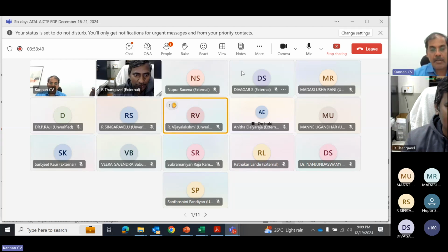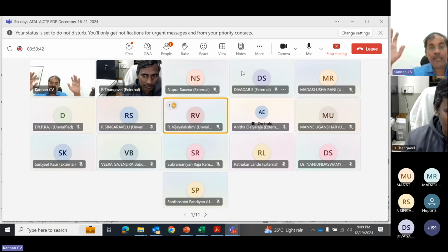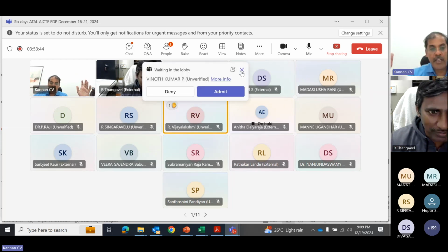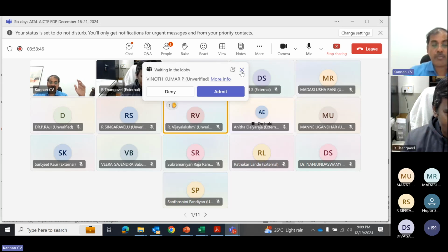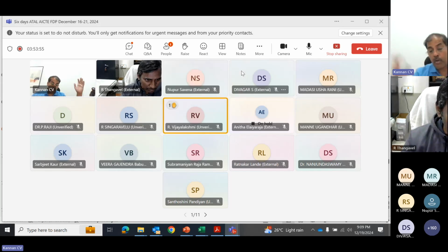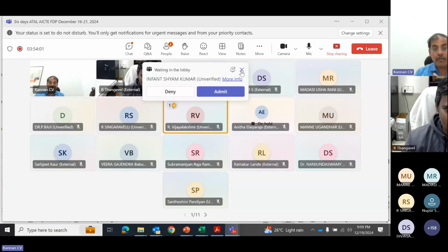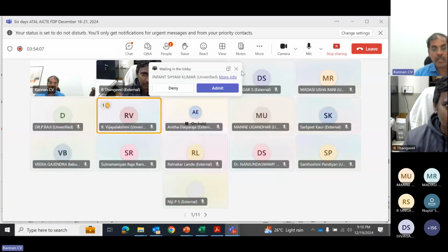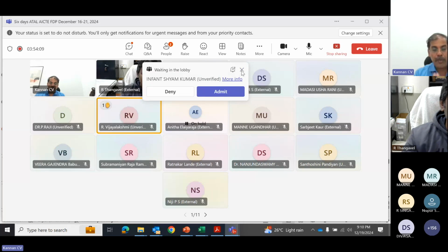But as I said, P-type also, after some time, has some limitation. You cannot increase the minority carrier lifetime beyond 100 or 150 or 200 microseconds, whereas with N-type based crystal or wafer you can go up to even 1000, 2000. So in between, the product becomes commercial friendly. Which technology, which wafer type is more commercially beneficial, an economically viable product? So that's why industry moved to P-type.